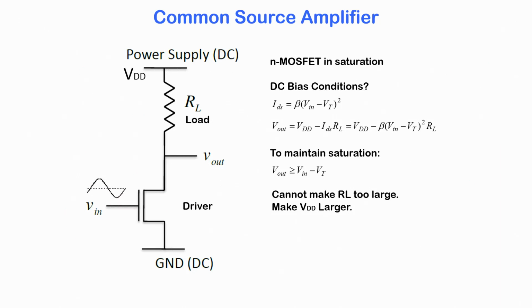The very first circuit we will study is a series combination of a resistor and a MOSFET. If you remember the two capillaries with water, we said that was the load and this is the driver. So, we have a load element which is the resistor, and we have a driver element which is an N channel MOSFET.